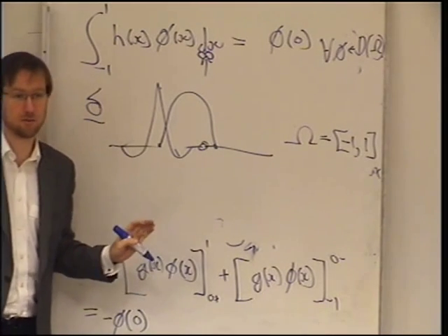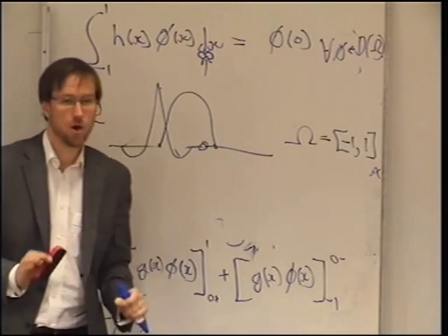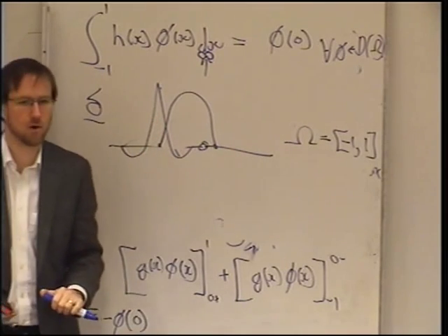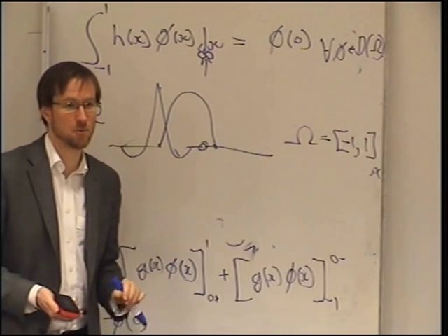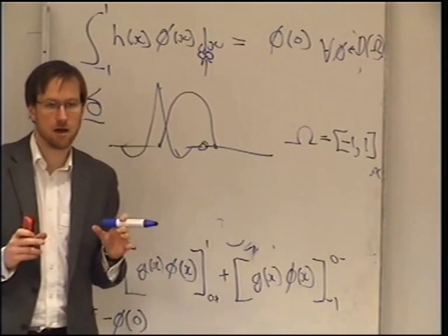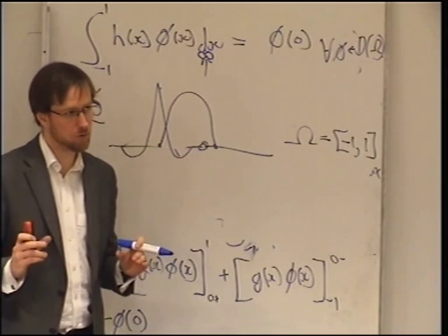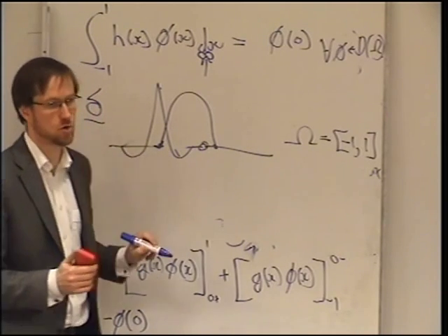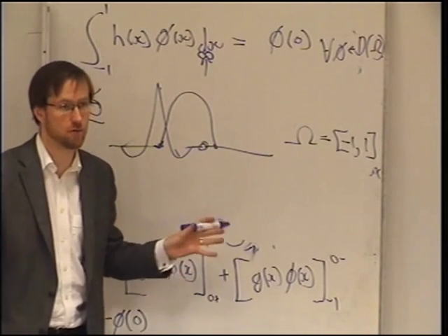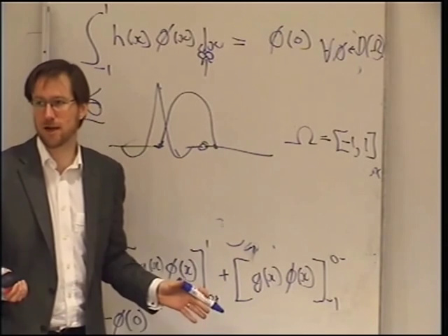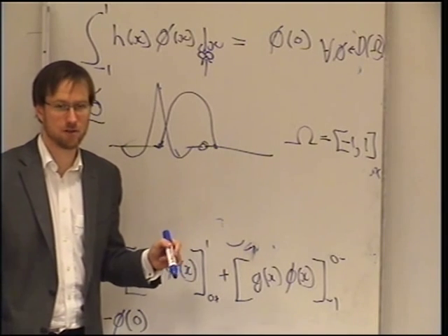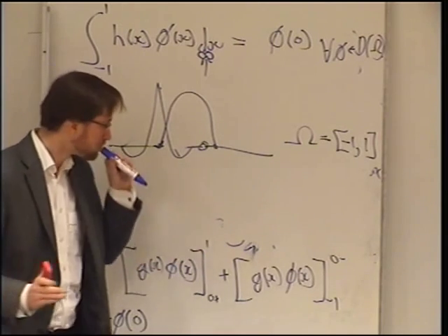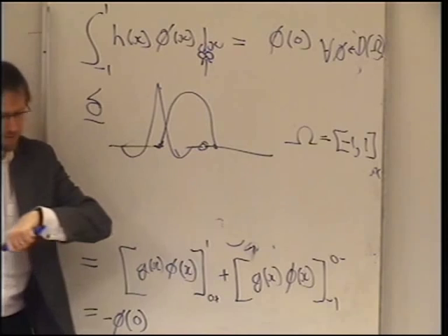In solids, when people are doing finite element methods for bending bars, and especially for making thin shells stand up, so if you want to work out the stresses in the Millennium Dome or something like that, then sometimes people will choose to use function spaces that are C1, so they are smooth at these points, which you can do if you jump through enough hoops. It makes the implementation hard, but you can do that. And that then means that you're allowed a second derivative in your operators, because the first derivative is C0, the second derivative is discontinuous, that's fine. So that is a permitted activity.